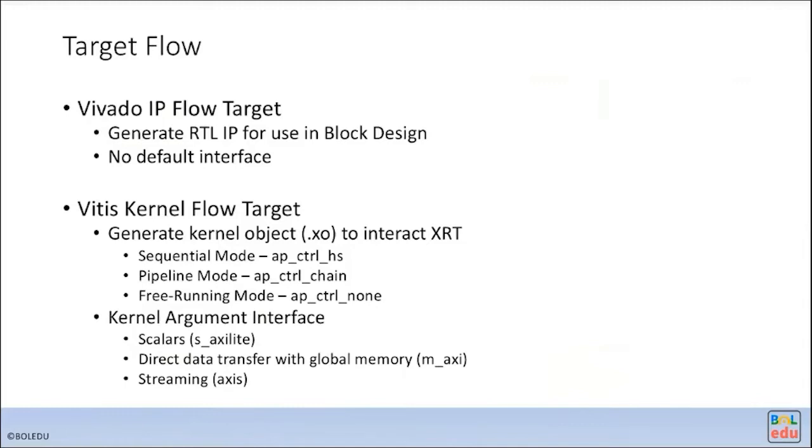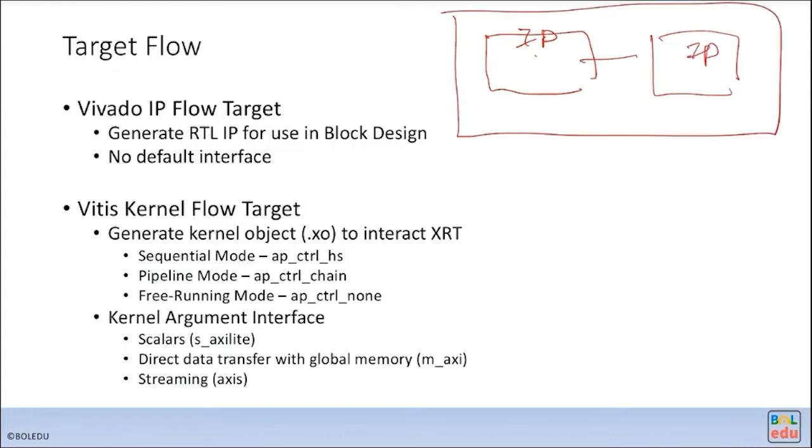When running the Vitis flow, you will specify whether it's an IP flow or the kernel flow. For the IP flow, it will generate a simple IP. This IP is mostly interfaced with other IP, and maybe with a wrapper that talks to the host programs. So that's the IP flow. For Vitis HLS, it's mostly the Vivado IP flow.